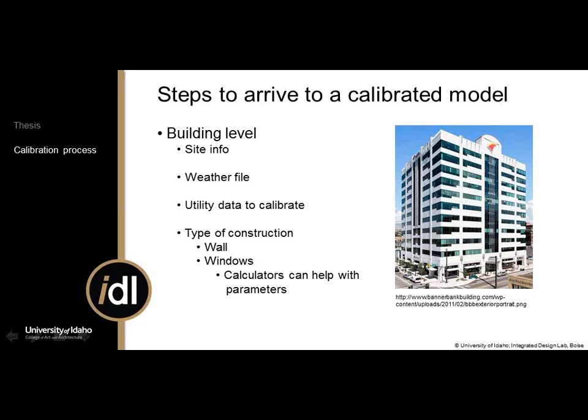It's amazing how difficult window specs can be to define on some of these projects. I believe on the Idaho building, we had to go all the way back to the mechanical engineers' HVAC calculations to figure out what the U-value and SHGC were. They're not in the plans. Rarely they're in the submittals. So it's something that's always kind of a difficult thing to do. So we've come up with a protocol sheet that has a lot of basic performance thresholds of different types of windows that we gathered from different research sources. So that's one way to get around that.